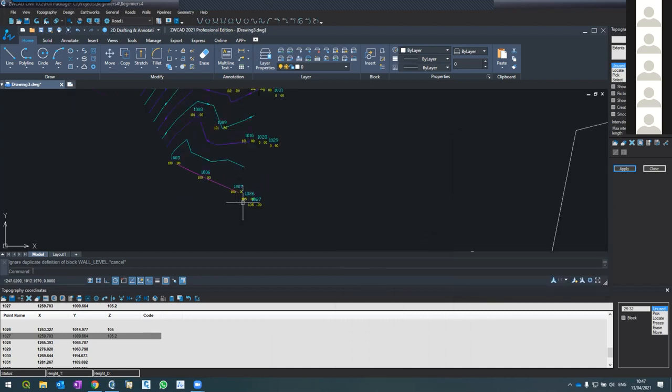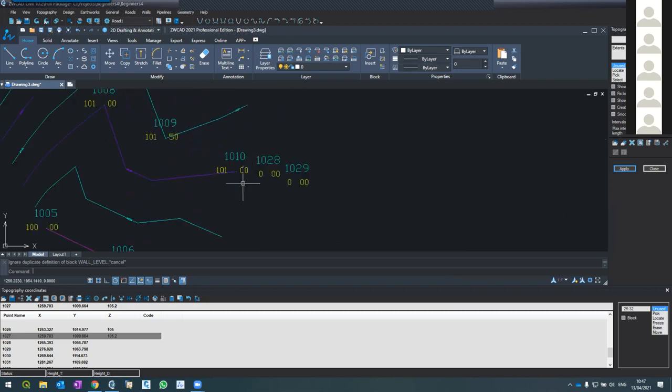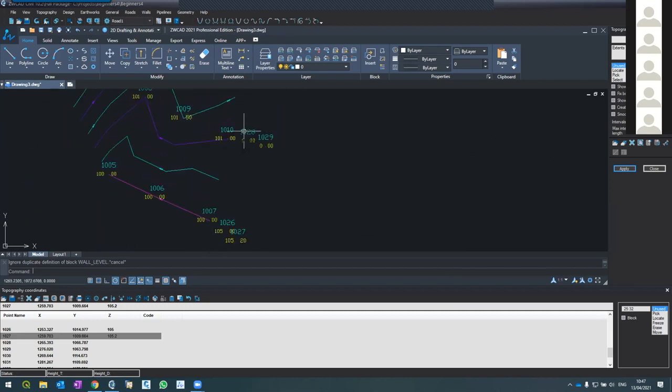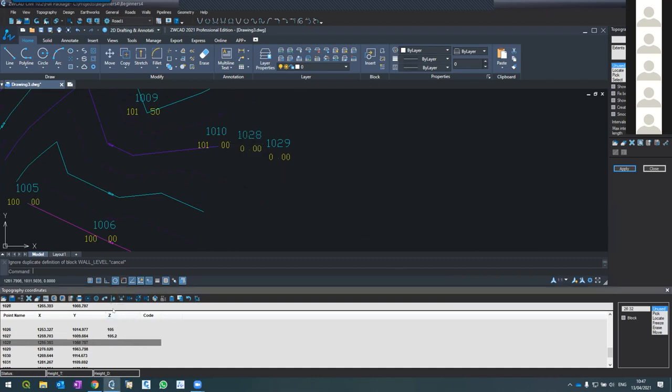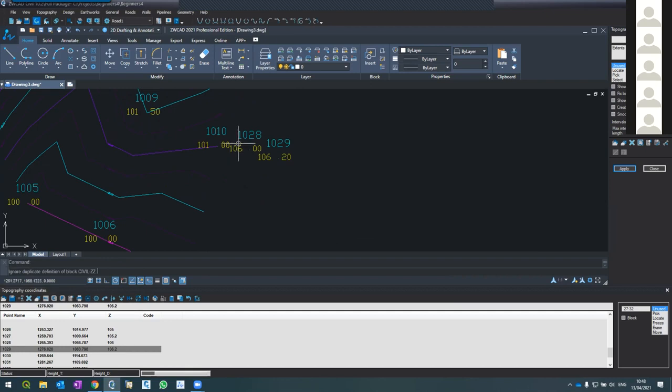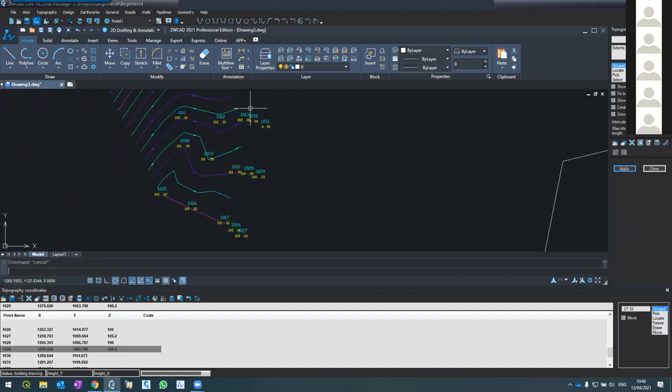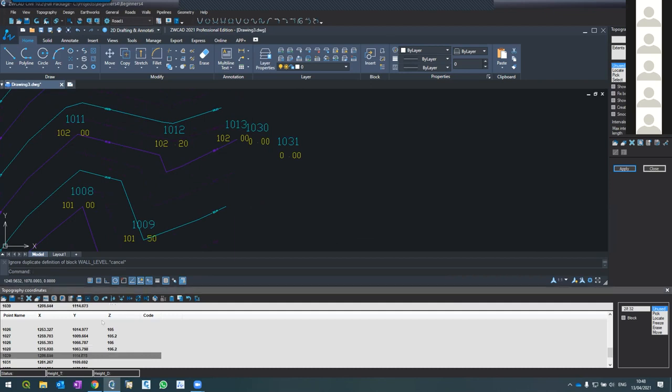Right. So I've added 2 points here, 2 points here. And again, here there's a jump. So here we put 5 meter. Let's put 5 meter as well here. So I'm coming here. And this is 101. This will be 106. And this is 106.2. And I press refresh. Okay, these are the 2 points which I measured here. And here this is 102, so this will be again a 5-meter jump. It doesn't have to be the same. Let's say a 6-meter jump here. So this will be 108, and this will be 108.5.